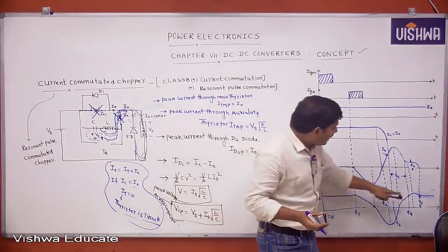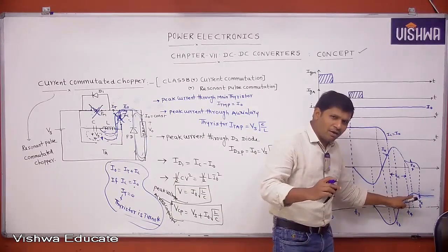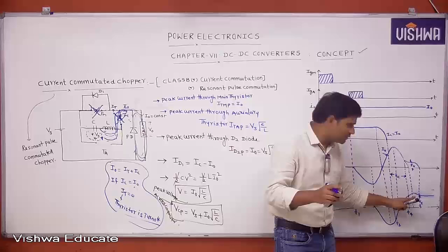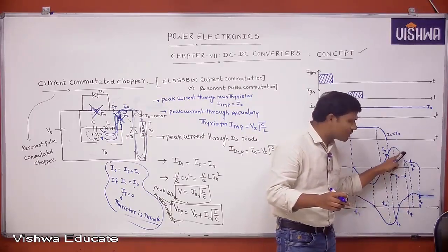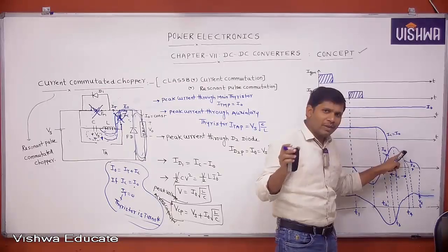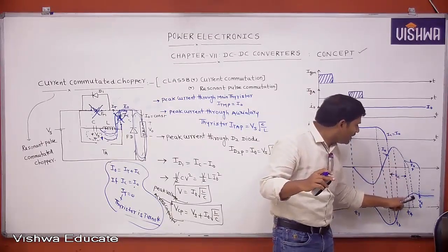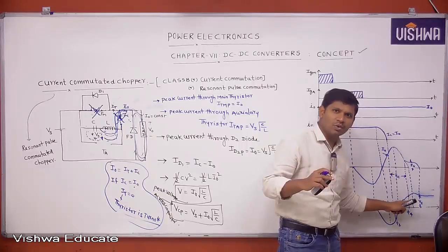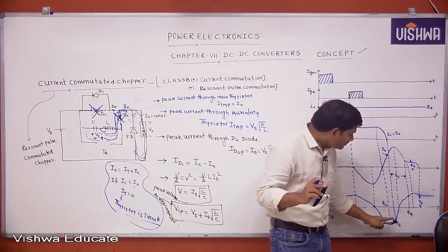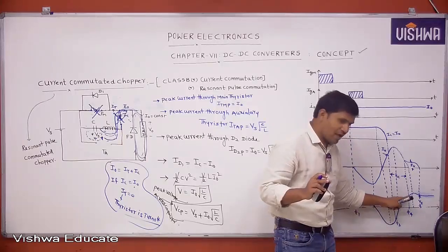Again it reaches Vs now. Neglect these oscillations and this transient voltage. There is some transient effect, because of the presence of the inductor and the sudden switching of the inductor and capacitor, there may be transient currents and voltages, no doubt. But the point to remember is that from t3 to t4, the thyristor is reverse biased.